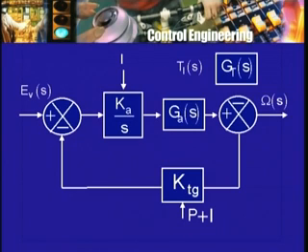Of course, we can apply the technique to a system where there is no integrator, that is, there is only an amplifier but no integrator. We will do that also. That is only the P controller, but we got into this whole thing because the P controller was not satisfactory. So let us first look at the P plus I or PI controller.